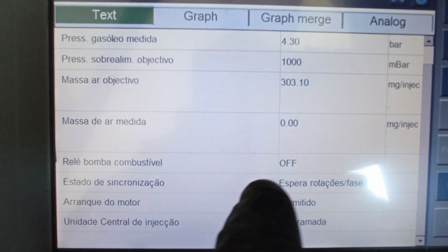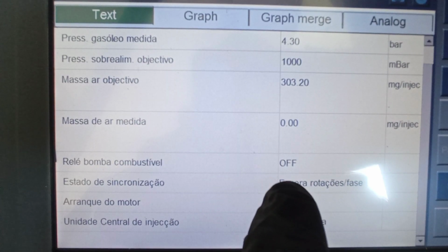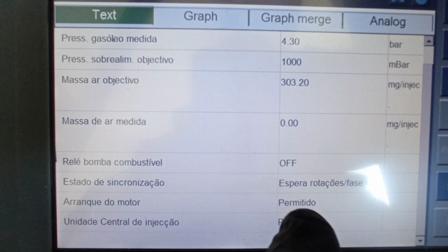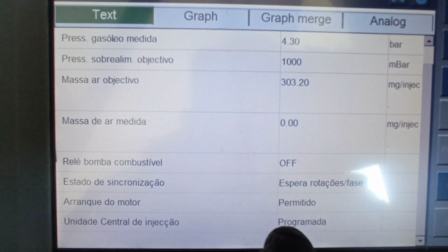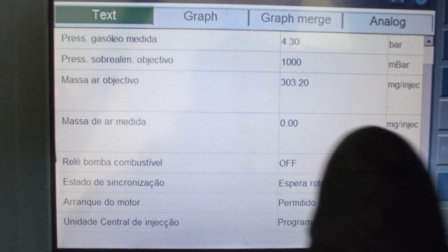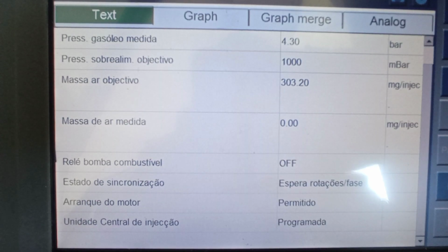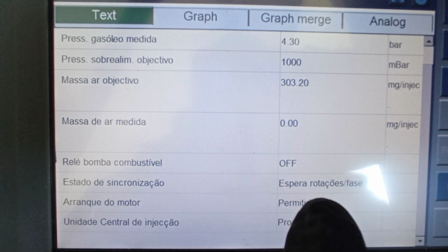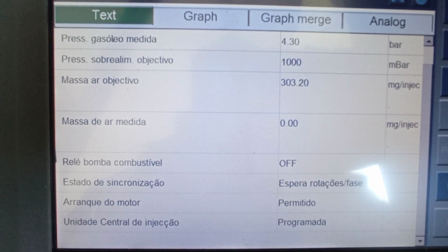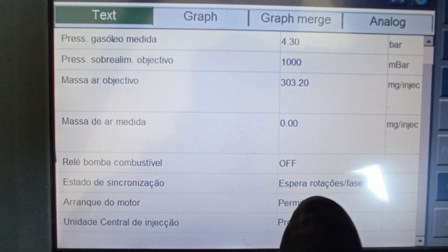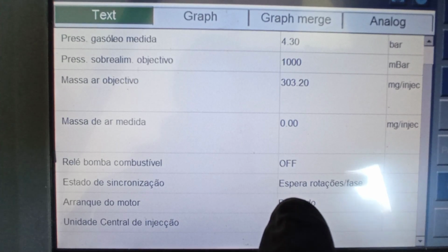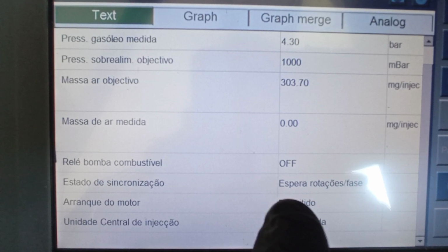We also saw that the fuel pump relay is working correctly because of the authorization of the transponder systems. About the transponder systems, I will leave it up here for you to see, and also down below. And we also talked about the camshaft position sensor. This is a very interesting one. The function of this sensor is varied, as you may have seen at this point.